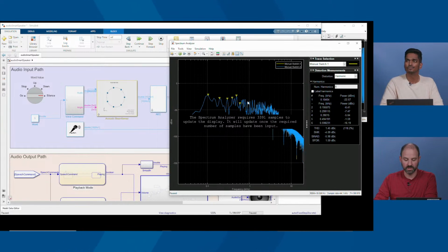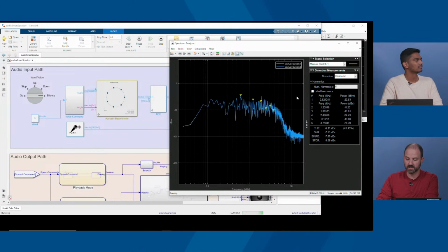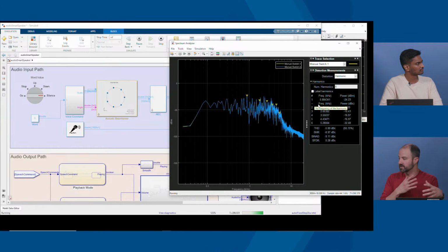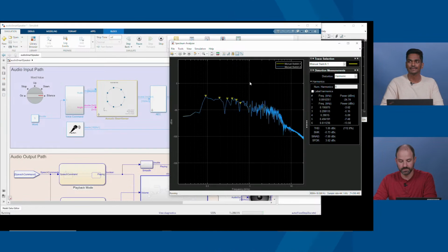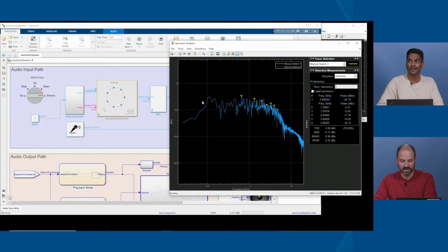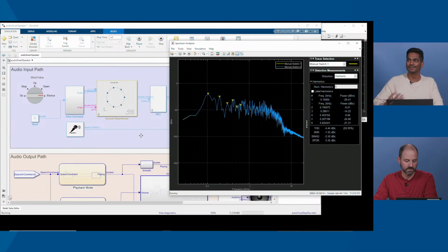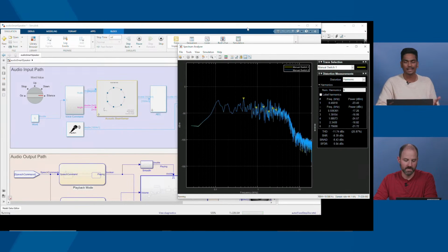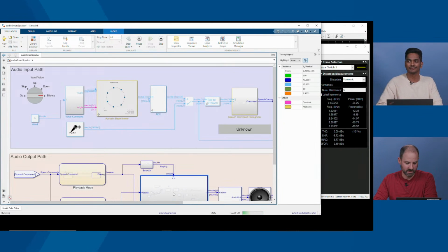In this case, we're looking at a musical signal, so I can't really extract that measurement. If I were doing test and measurement, I would feed in a sine wave or something like that. This is a more complex signal with different frequency components, so it's spread over different frequencies. But with a chirp signal or a sine wave, the harmonics become apparent.